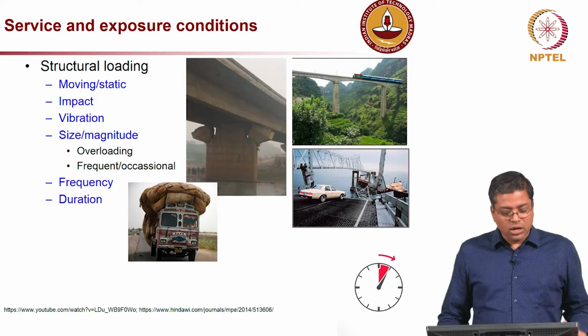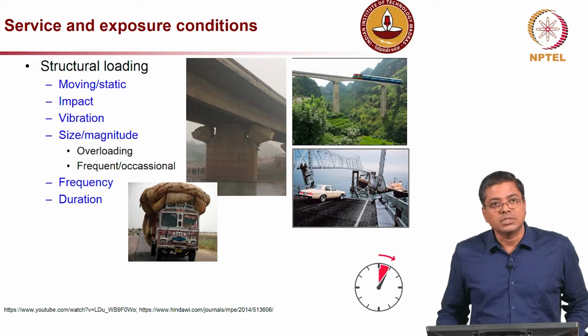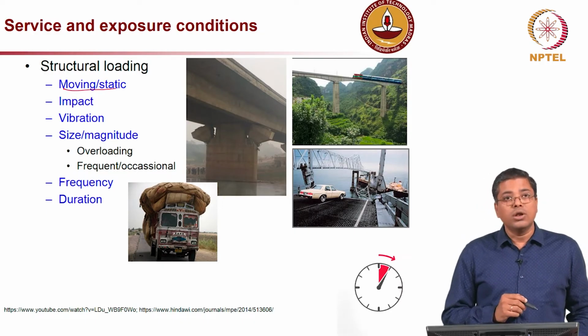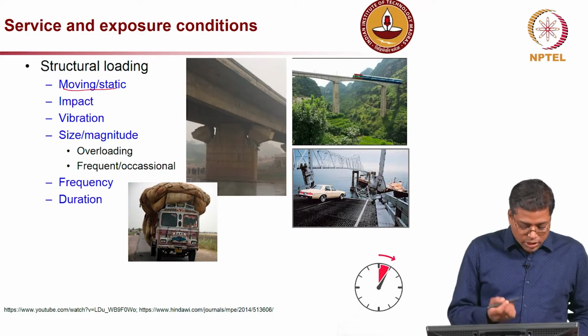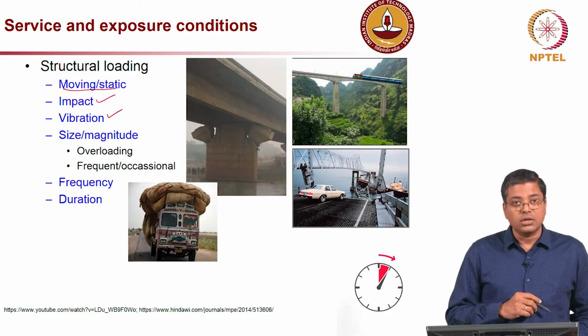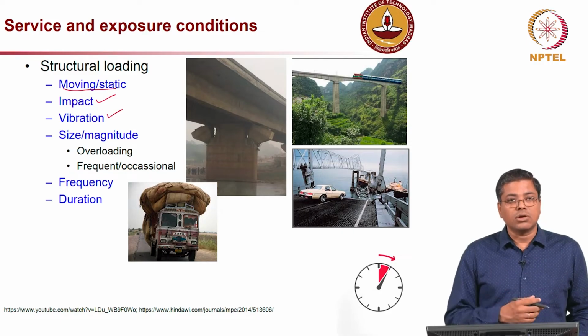Now, when you talk about service condition, which is essentially the structural loading conditions, you can have moving loads or static loads, dead and live loads, and then you can have impact load and vibration, if you are talking about a bridge structure.